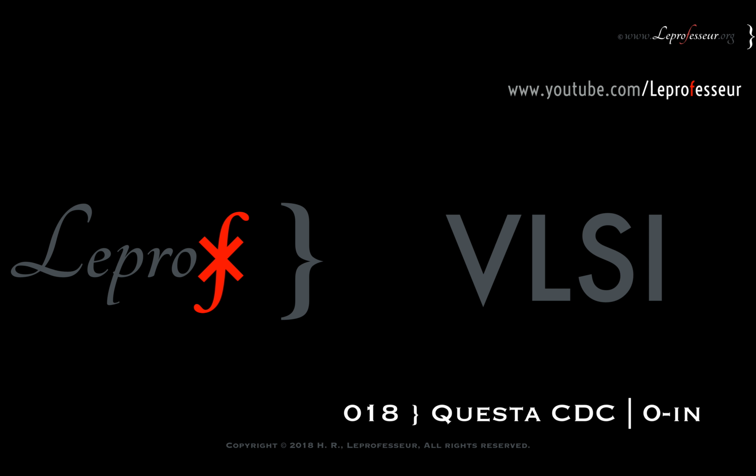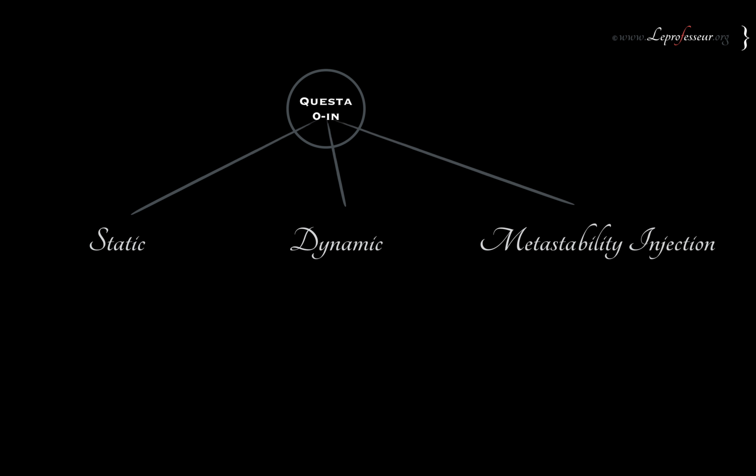A basic overview about the tool. The Questa CDC 0-In tool works in 3 stages: static, dynamic, and metastability injection. So first, you would want to clear your CDC violations in static mode. After you are satisfied with the results, you have created necessary waivers, and there is no error or no CDC issues during the static